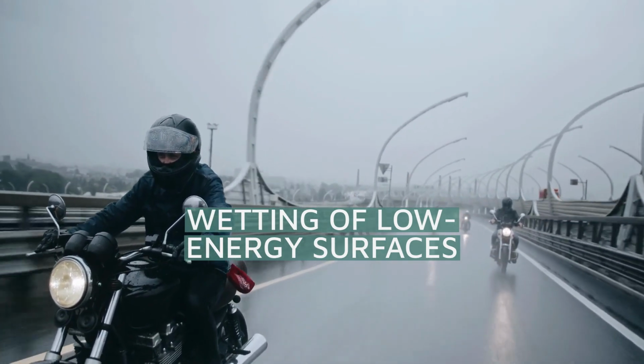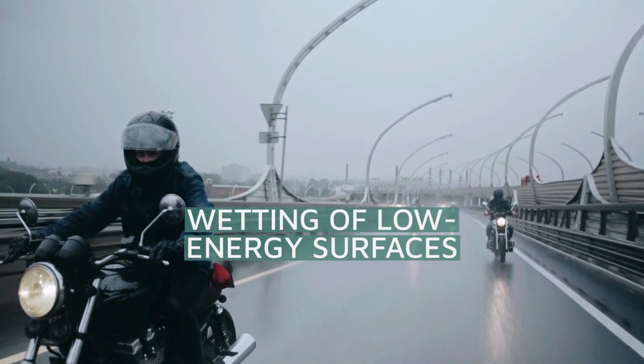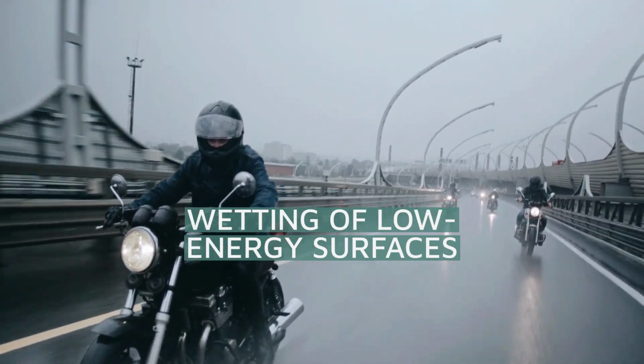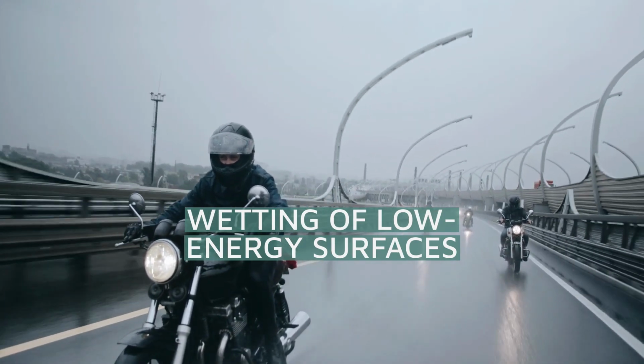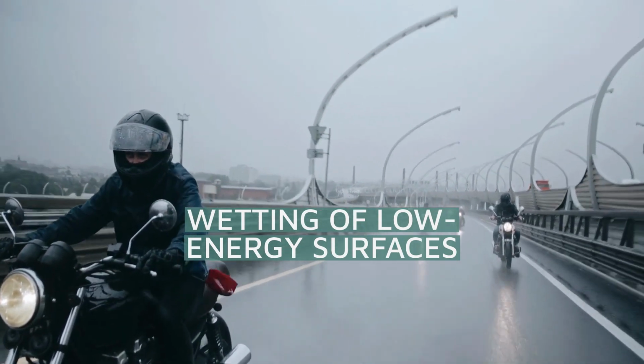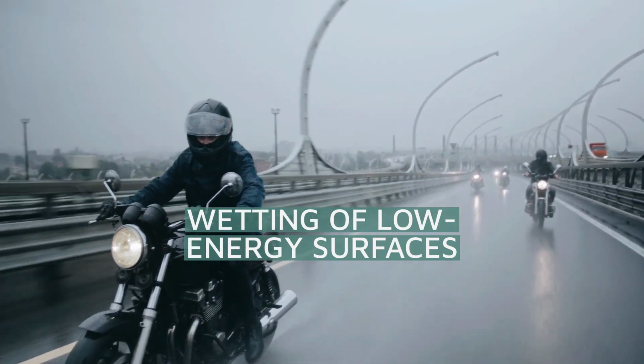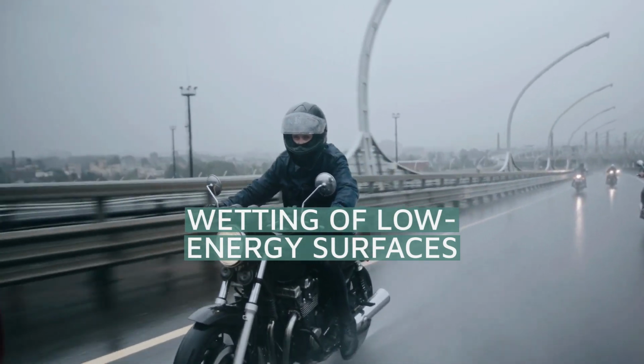Zisman termed the intercept of these lines when cos theta equals 1 as the critical surface tension gamma c of that surface. This critical surface tension is an important parameter because it is a characteristic of only the solid. Knowing the critical surface tension of a solid, it is possible to predict the wettability of the surface.